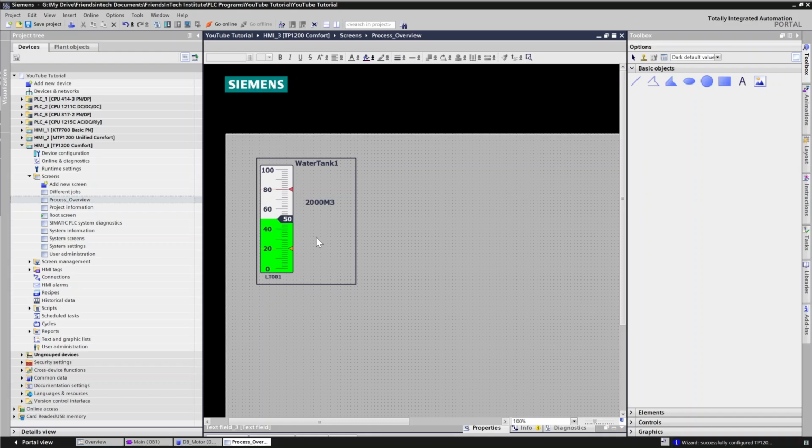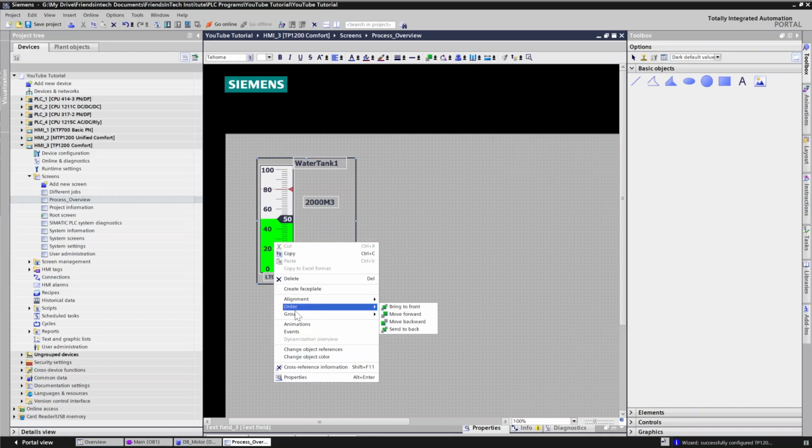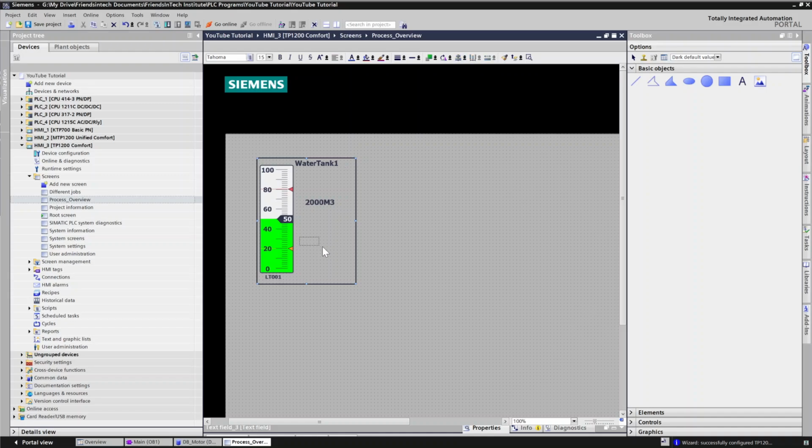So you can decide to add indication, numeric indication for temperature, but that's okay, because the idea is how do you convert this one template into a faceplate. That's the thing, that's the goal. How do you convert this into a faceplate? Now if you have this here, you need to convert this to a faceplate. So what you can do here, you can just select everything and then you can group this. Okay, you can group it. So that is one thing, it's just one object.